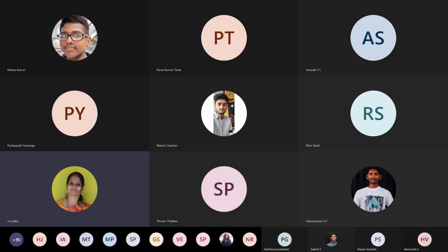Another category of parallel projection is axonometric projection. It is further classified into trimetric, dimetric, isometric. The third category of parallel projection is oblique projection, cabinet and Cavalier projection. And the perspective projection is categorized into three: 1 point, 2 point and 3 point. We are going to discuss each and every projection with example problems.